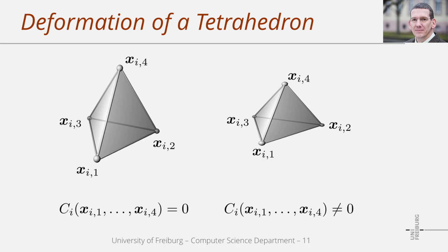We could measure that a tetrahedron is compressed in x direction but stretched in y direction. Or we could represent shear. Using just one number to represent a deformation does not allow to handle such aspects. Nevertheless, the concept for the force computation is always the same, independent from the complexity of the deformation function, and I would like to keep it here as simple as possible.